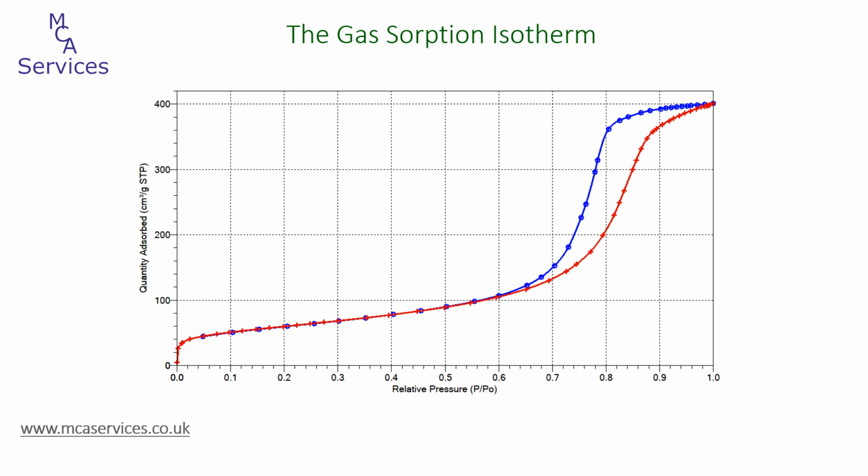We use the technique to characterize a sample's porosity, or the porous nature of a material, and from the various parts of the isotherm, we can obtain varying information. At the low relative pressure end, we can look at micropore volume, area and size. A little higher up on the adsorption isotherm, we can look into specific surface area, most commonly BET surface area.